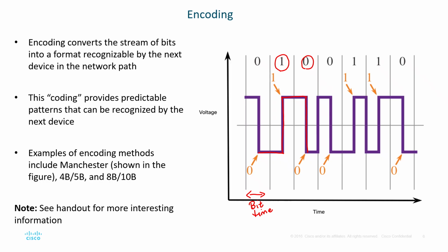Okay, and now because there's two zeros together, in the middle of the bit stream here, it goes high, and then it goes down low again to the next 0 here. And then again, next bit stream, it goes high, and vice versa. That is how Manchester encoding works.